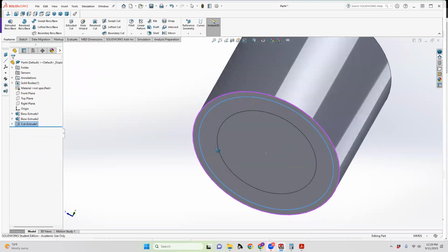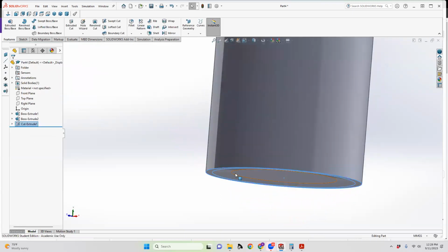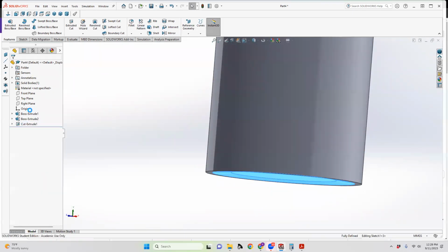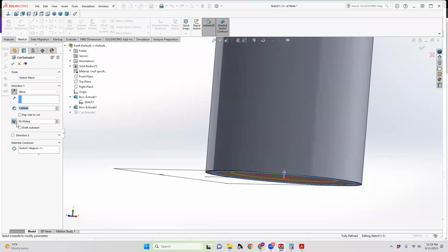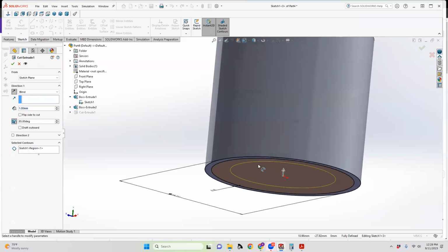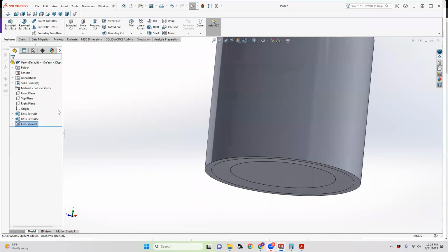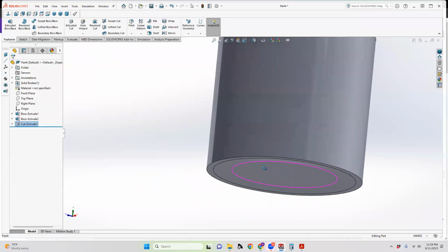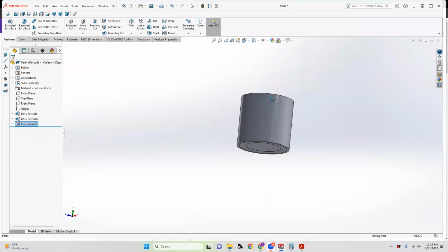And this will give us that indentation on the bottom by doing that tapered cut. So you can also do tapered extrudes, but this is a tapered cut. So that'll give us our coffee ring maker at the bottom, because that's essential for any World's Best Dad mug, right?